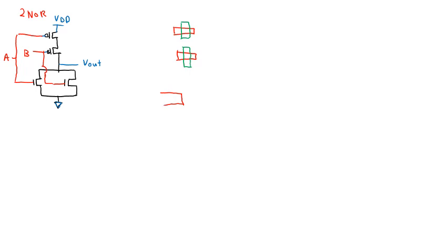And then we should draw the NMOS in parallel. So you have this one, and overlap the N diffusion on top of the polysilicon, and then we give the ground. If you look at here, this is the source side of both NMOS, so you can put these two. Oops, sorry.